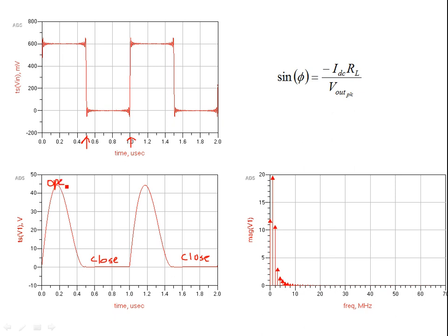So you have this pulsating trend in V1, which is due to the opening and closing of the switch, since we are treating the JFET as a switch. This is about a 50% duty cycle, and here again you see this is about a 50% duty cycle.